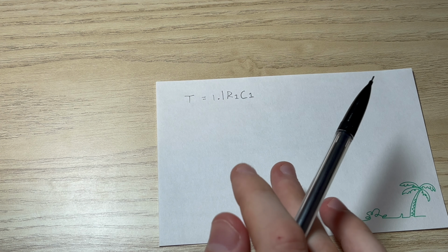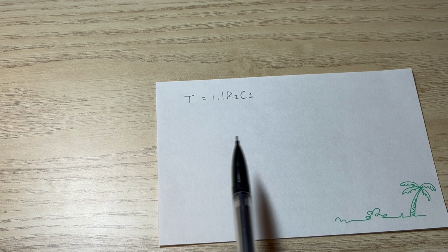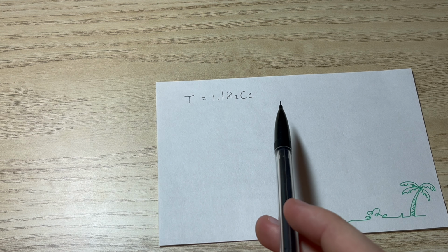That's it. It's essentially just multiplying the resistance and the capacitance together, and that would be your time period. You could easily go online and use some online calculators, and that'd probably be easier, but here's the paper version. You could tinker around with these equations to get milliseconds of time or seconds of time.